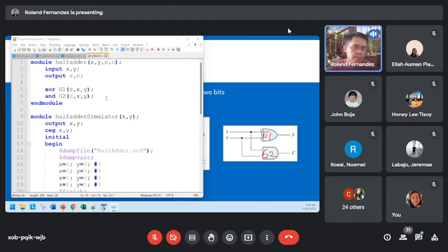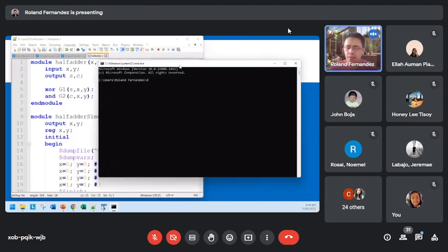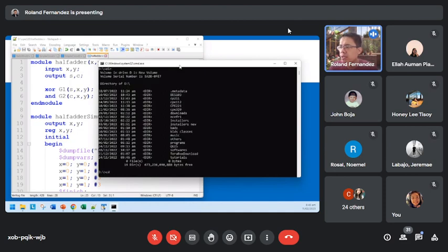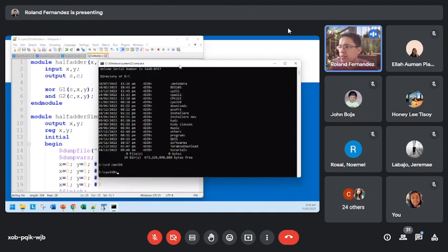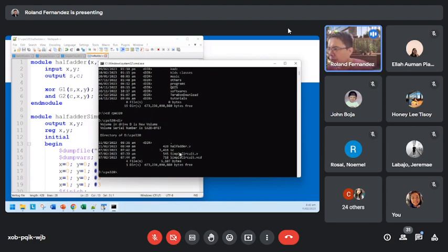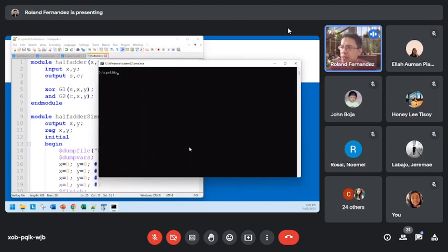We say, then we'll try to use MD. So we now go into our drive D and the DIR. We go into CD CPE P20 DIR. So this is now our code, the half-adder.v. So, okay. So we now try to say iverilog -o, and then the output file name HA. That's for the half-adder 1.